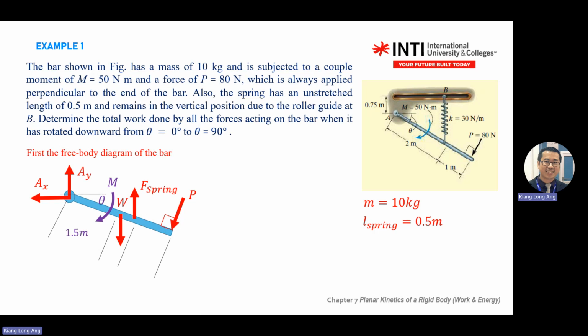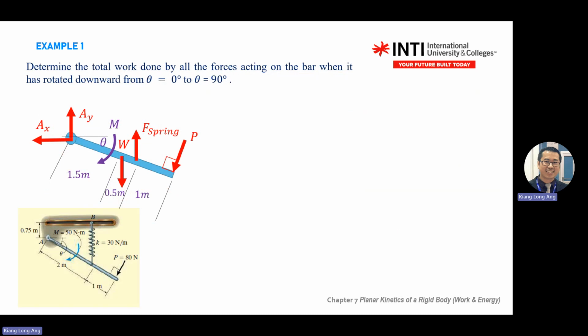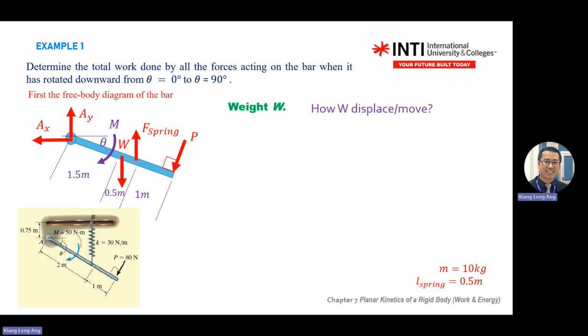Now, as you move into chapters 6 and 7, your free body diagram will include force and moment. A particle doesn't have moment because you see it as a whole big body; moment happens inside, you cannot see it. Then you put in all the parameters, all the distances, and so on. Then you start to look for displacement, which means you do work analysis.